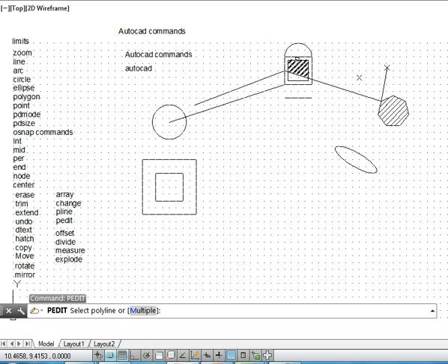It has other ways, other options also. I'll take you to them also. But before that, what I do, so PEDIT. So when I type, I want to convert normal lines into P lines. So I'll demonstrate this capability of the PEDIT command.